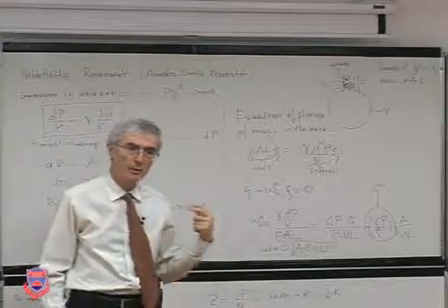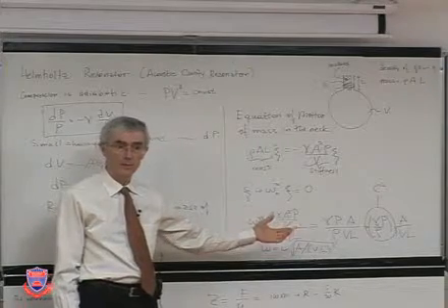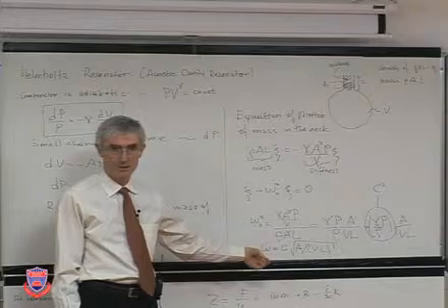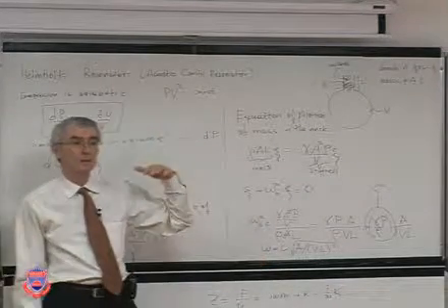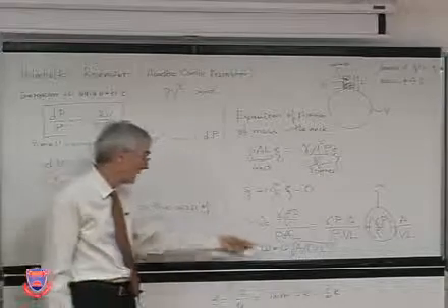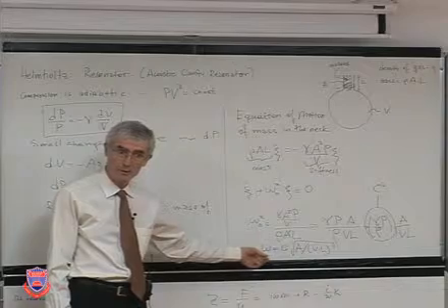So if you have a different gas, helium, for example, you're going to have a very different resonant frequency. Or if you're at very high altitudes, temperature is different, speed of sound will be somewhat different, so you have a different natural frequency.